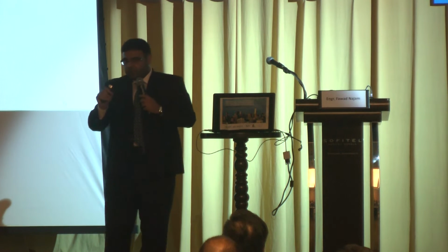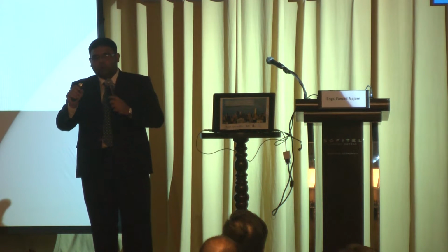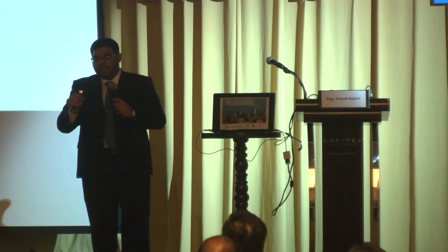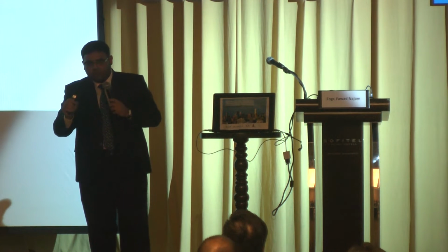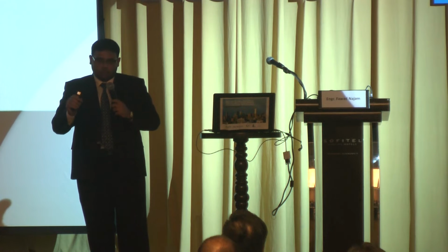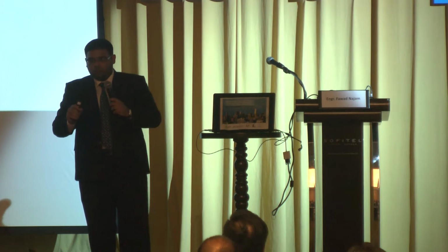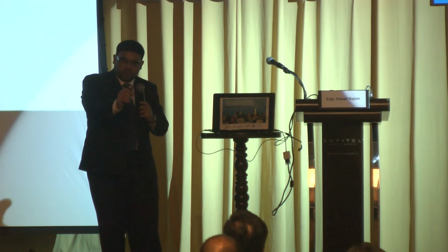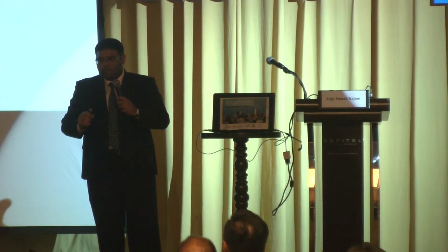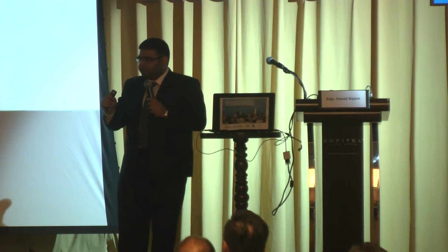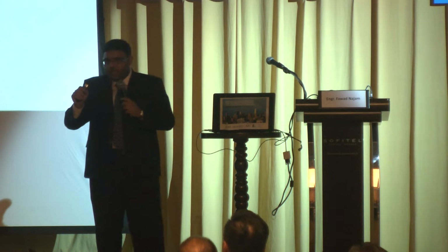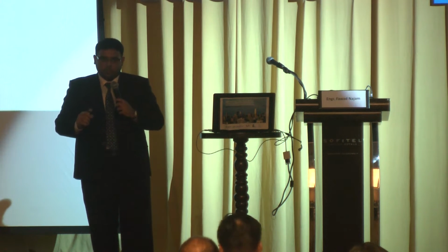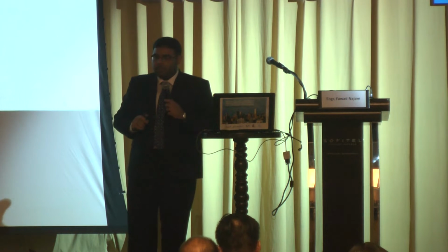But those engineers said something which was kind of awesome. They said that we don't want additional security. We want confidence in our understanding of that structure. We want to know crystal clear that this member should be in tension, this member should be in compression. We preferred the understanding over a false sense of additional security in the form of redundancy. So we want the structure to behave simply.